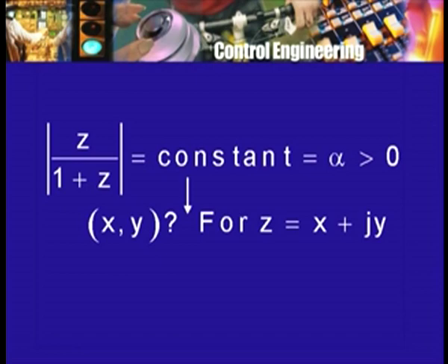Of course, the contour map shows you the actual height, or the equipotential lines show you the actual potential, whereas here these M circles, if I can draw the whole set of them, would give me the value of the closed loop gain corresponding to a particular point in the complex plane, which may be the value of G(jω) for a specific G and a specific ω.